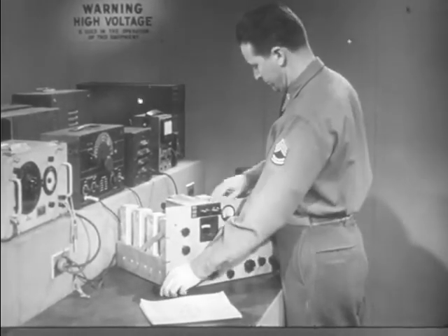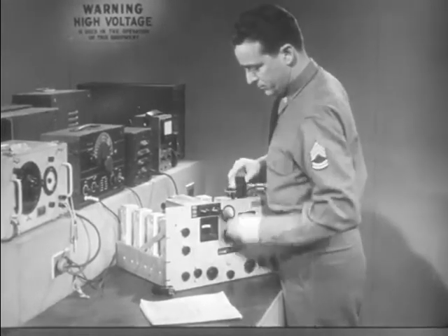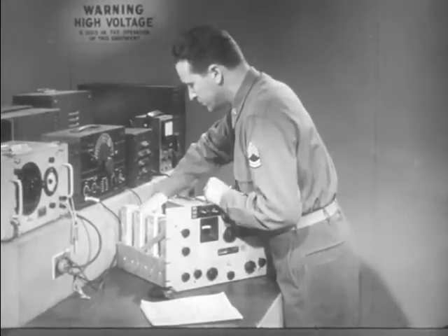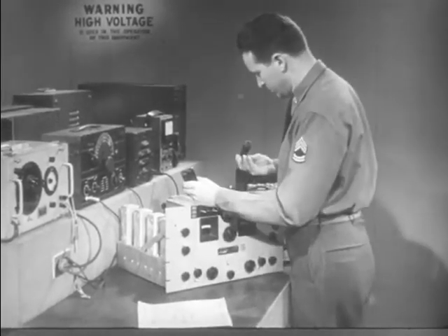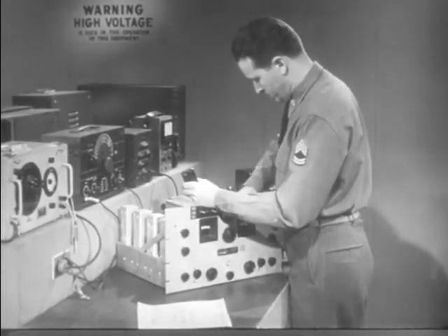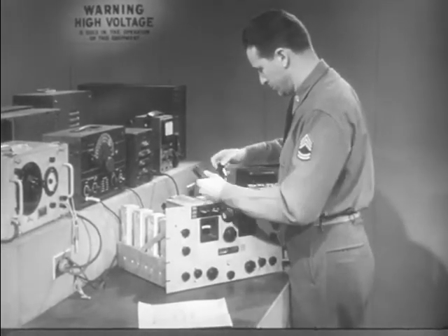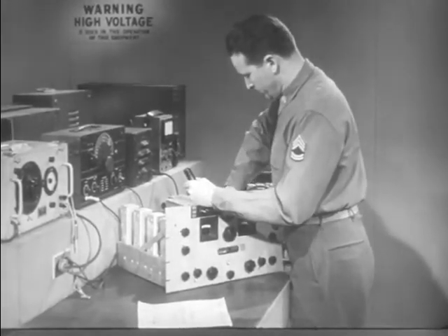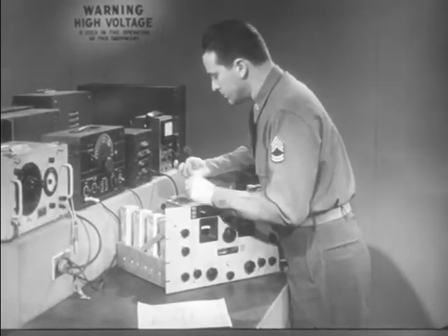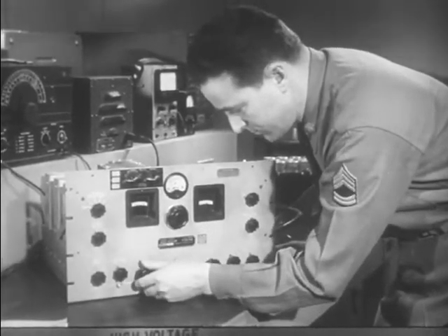Now returning to the radio receiver, before it can be aligned, it must be checked thoroughly to eliminate all other defects. Tubes are checked, voltage tests made, and a careful visual inspection accomplished. Aligning a set that has other defects only means repeating the whole process again, since change in the constants of the set, such as a new tube or capacitor, affects the alignment. So repair first, align last.